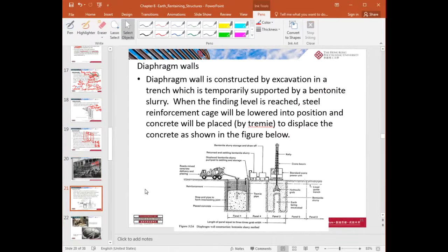And also you have learned about the diaphragm wall, right? Under the construction technology and materials course, you have learned about what's a D wall, right? That is the D wall, diaphragm wall. So when you are doing some excavation and then infill with the bentonite, sometimes called slurry wall, the slurry will support the ground from collapse, right? Because you are digging a trench.